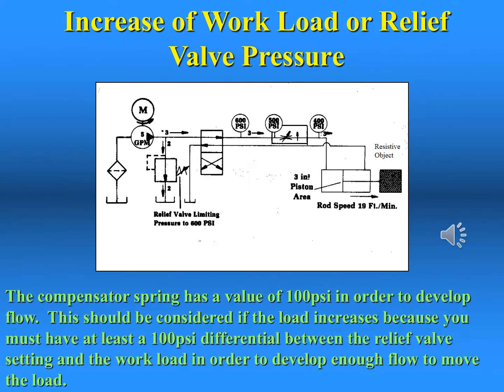This information has already been explained, but the relief valve is the voltage regulator of the hydraulic system. It brings to point an important advantage that fluid power systems have over electrical systems. If the demand for pressure of the load exceeds the limit of the relief valve, the cylinder will stall out. If this were a hydraulic motor instead of a cylinder and an overload was applied, the motor would simply stop. If you did this to an electric motor, the overloads would trip or the motor would simply burn up.